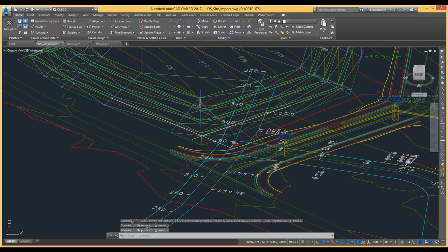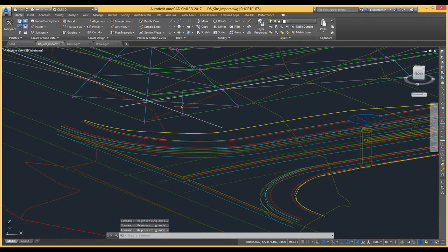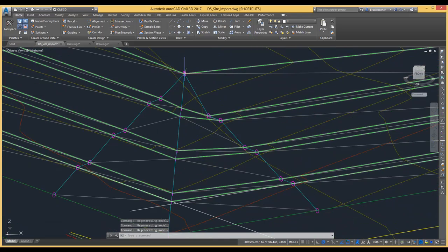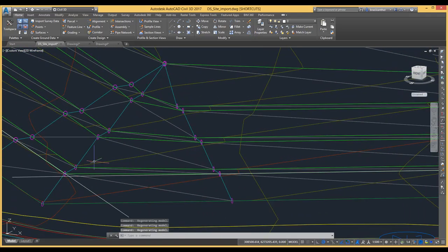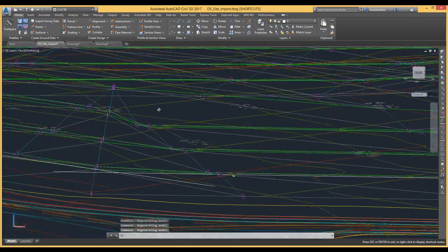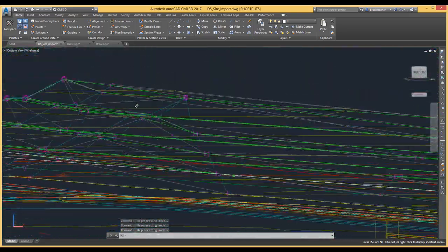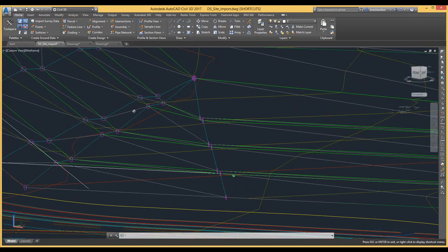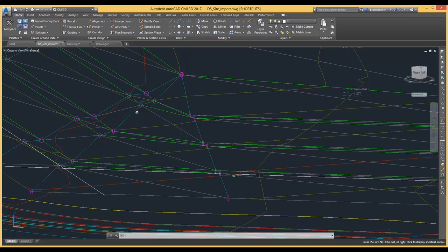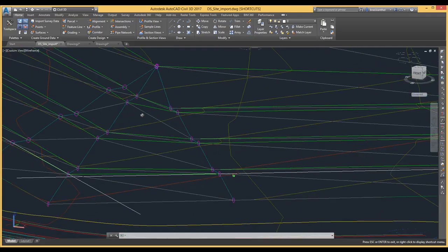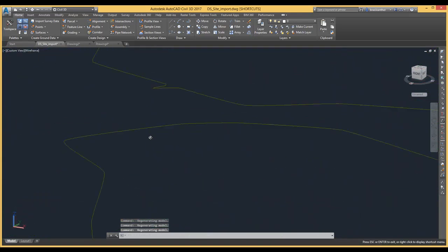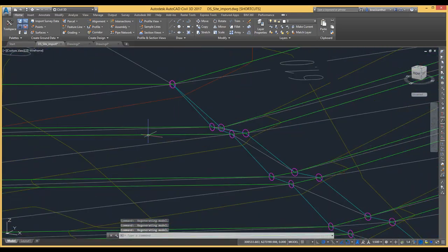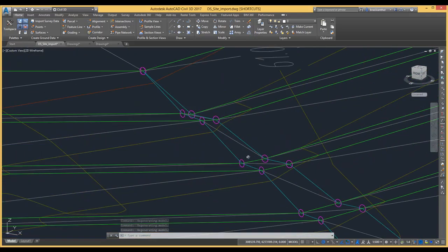You can see that it tries to sort of average the slopes out between the last section before the turns, the corner on both sides, and it builds the main section up from the corner, but the results aren't always what you would expect. There are no options or parameters you can change to determine how this corner resolves itself. You just have to keep tweaking and playing with the elevations on the rest of the feature line to see how it's going to resolve. Obviously, the more rapid the transition is, the better it will be. The more subtle the transition is, the easier it is for it to resolve.